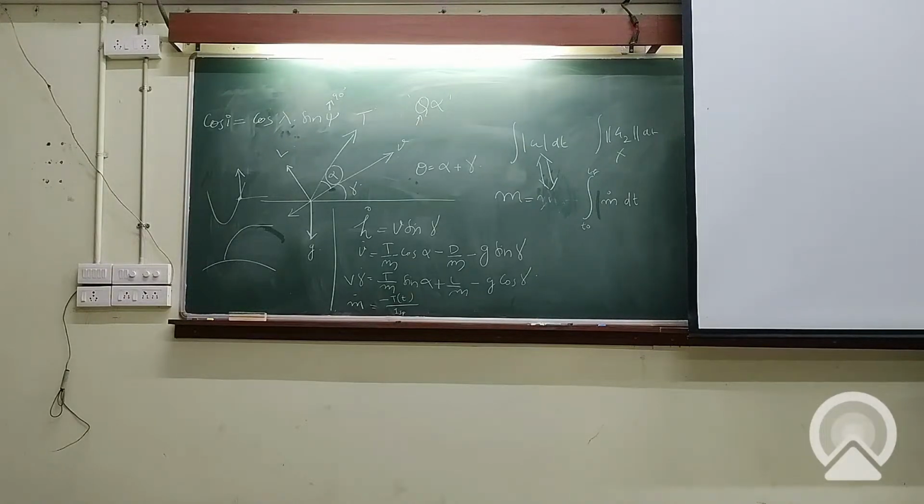And this impact constraint is very critical when it comes to the second stage. Because the first stage is still okay. You will be close to the mainland from the place the launch happens, and more or less it will be sea, so impact will be happening in the sea. But that's not the case for the second stage. There may be land masses there. Right? So you cannot discard the second stage wherever you want. You should make sure that it doesn't go and impact on a landmass. That is a very important constraint.